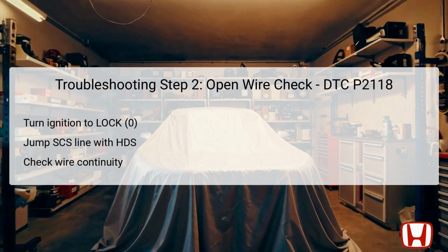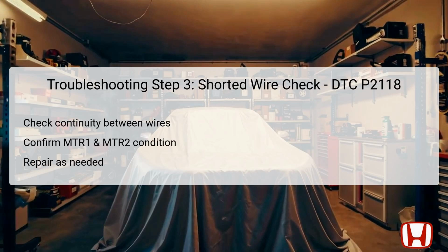With these connectors removed, check for continuity between test points 1 and 2 of the SG3 ETCS line. This will help determine whether or not the wire is open. Continuity must exist for the circuit to be intact. If it does not, you need to repair the open wire in the SG3 ETCS line before proceeding to further steps. In step 3, you will check for shorted wires in the MTR1 and MTR2 lines.